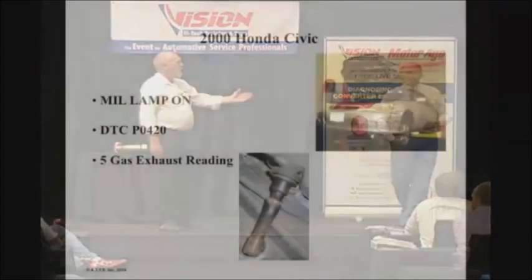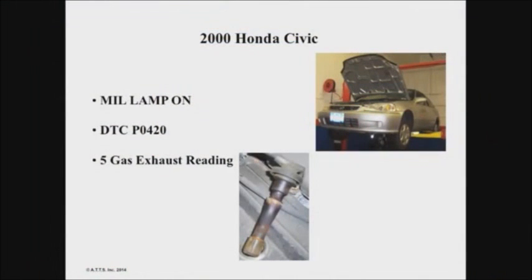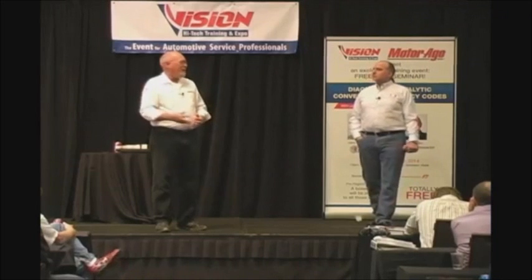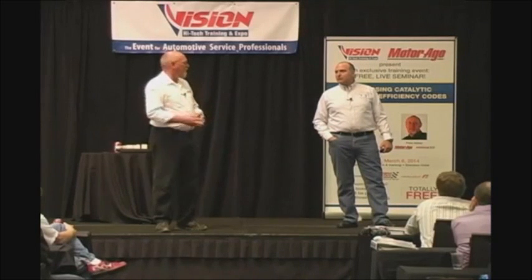I want to put a word of caution here that some of the exhaust manufacturers that we spoke with want to caution us about. When you do the carbon cleaning, especially in some of these GDI engines, you've got to be careful of where those chunks of carbon are going, because you could create a situation that leads to a cat failure if you're dealing with a heavily carboned up engine with a lot of miles on it that hasn't been maintained. You could be setting the stage for that problem.